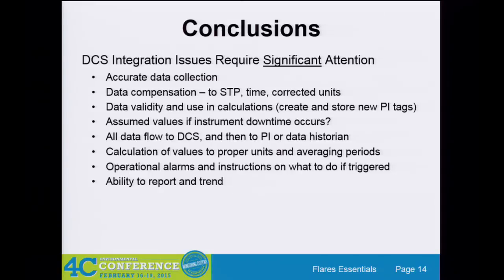Use a voting system so that as long as 2 of the readings are within a certain amount of each other, I know that I have a good temperature reading. If that third one is consistently out, it's now been flagged for maintenance. So hopefully with 3, you should never have a data issue due to a temperature probe.